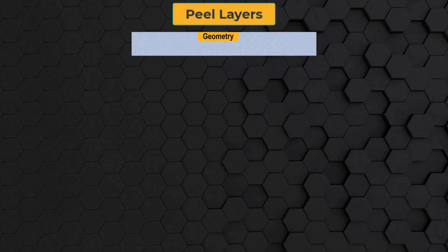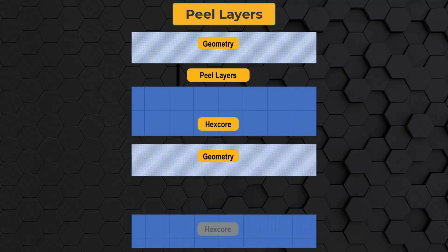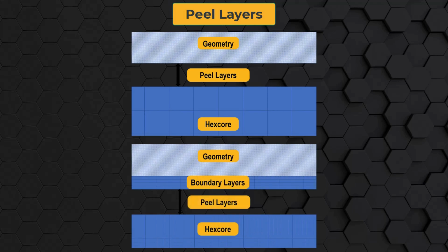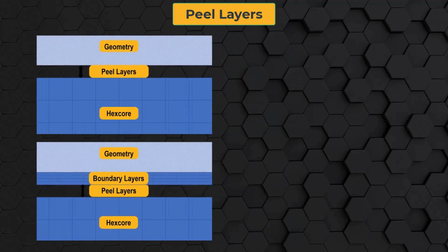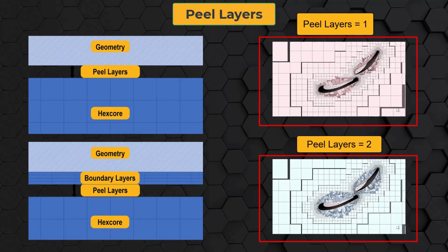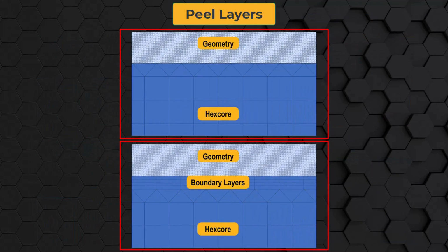Next, field layers control the gap between the Cartesian mesh and the geometry or last layer of boundary layer mesh when they are included in the computational model. The smaller the number of field layers, the closer is the Cartesian mesh to the boundary surface or the boundary layer mesh, and vice versa, as can be seen from these two images. The gap is filled with tetrahedral elements which act as transition cells between the triangulated surface mesh or the boundary layer prism mesh and the core Cartesian mesh.